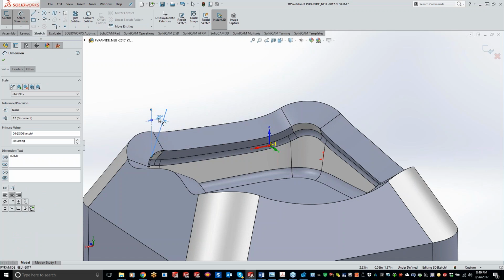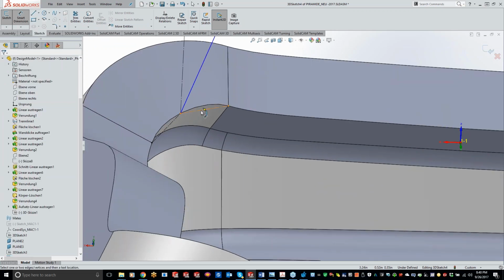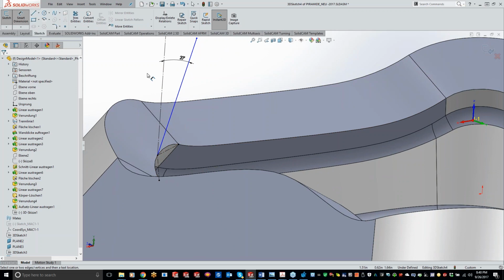So it's pretty much as easy as that. If you guys are running splines, that's where the biggest issues come into play, not being able to snap a midpoint or anything like that. So that's where these two lines really help out, finding the midpoint based off of this line being exactly equal to this line. It's going to bounce right to the middle, and then we're able to grab that straight line coming up and going out.